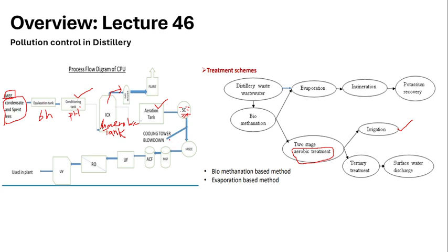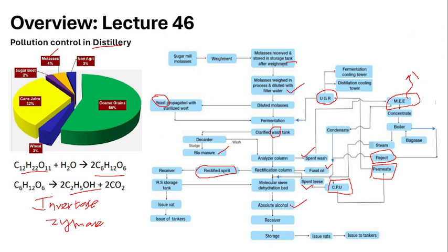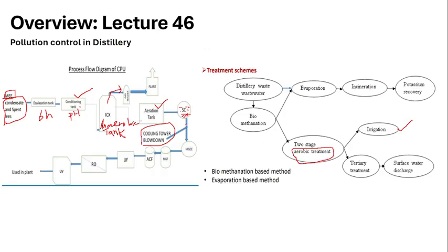Okay. And then we have the second inlet, which is nothing but our cooling tower flow. We have two different cooling towers. One is the fermentation cooling tower and another one is the distillation cooling tower. All the waste stream from these towers comes directly here to the further advanced clarification step. Here the high rate clarification tank is there. In this one, along with the solid and water, it is again getting treated. Okay. So after the high rate secondary clarification, we have the next filtration steps.